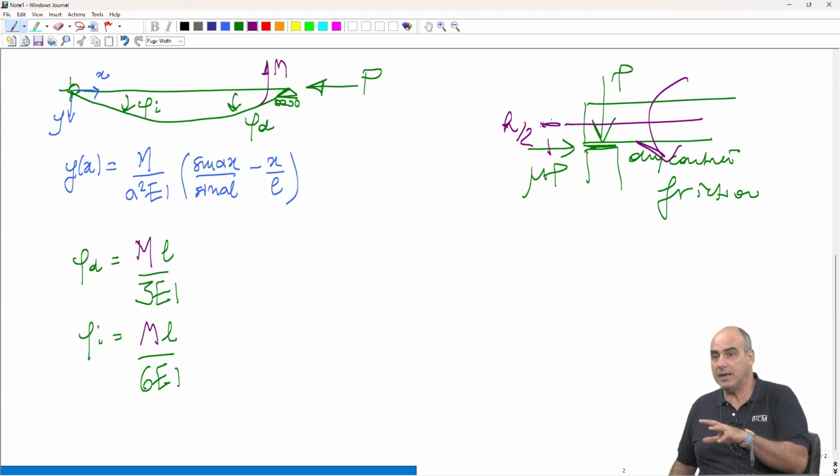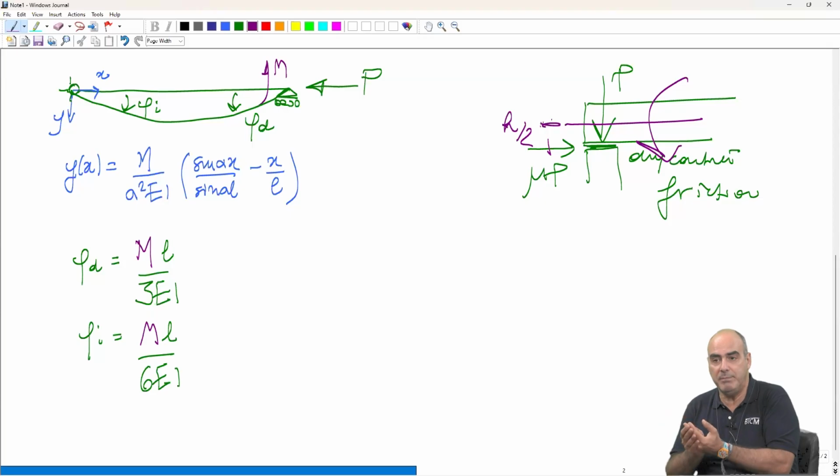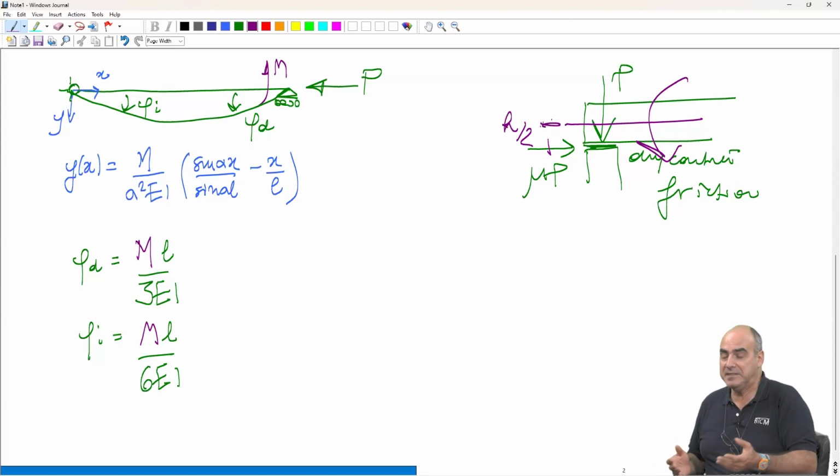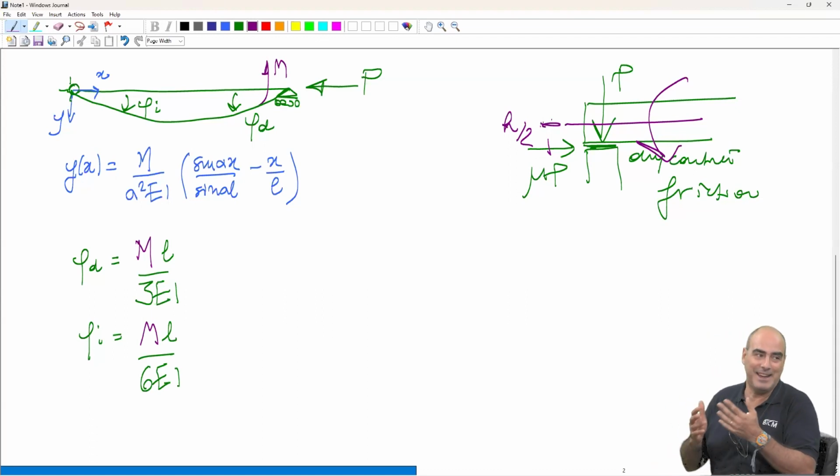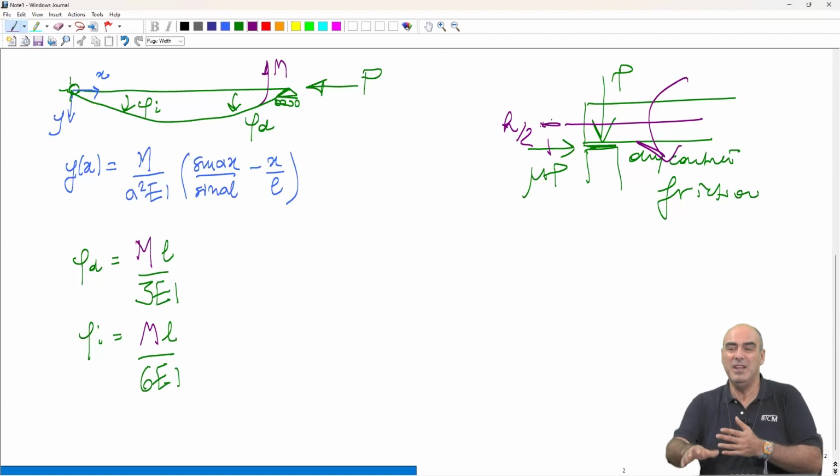But in some structures, for example steel structures, these moments add additional stresses on the bolted joints typically. And bolted joints can fail. While in a precast structure you say, okay, I can expect cracking, and cracking may not be so severe. You cannot expect failure because of this.